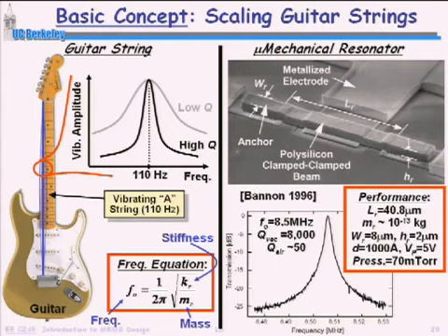To give you an idea of how selective that is, if you take a transistor circuit and you use the inductor that's available in your transistor technologies, what Q will an inductor give you? Spiral inductor in an integrated circuit transistor technology. Does anyone know? EEs? 5 is respectable. You're lucky if you get 10. This is 8,000. And that has to do with mechanics versus electronics.